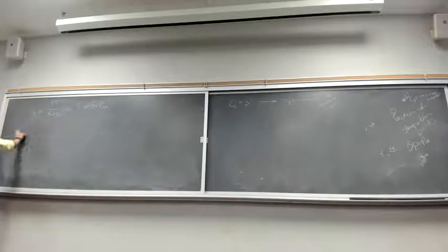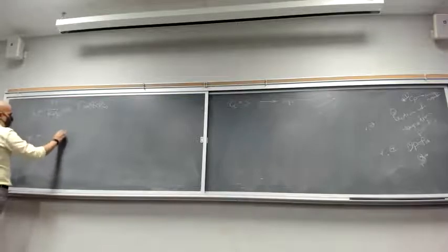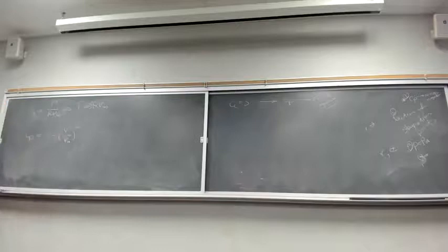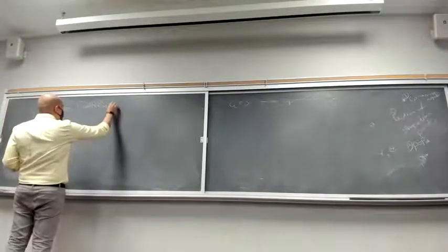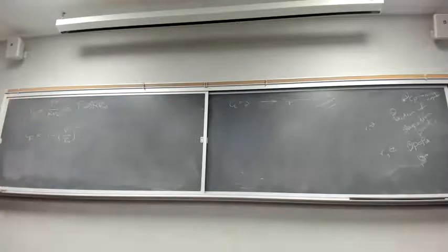What do we want to find? We want to find the most negative CP. So CP is 1 minus V over V infinity squared, right? Can actually rewrite this as a function of V infinity. Okay, do we have the velocity? What is the velocity? What was the equation for velocity we have had?